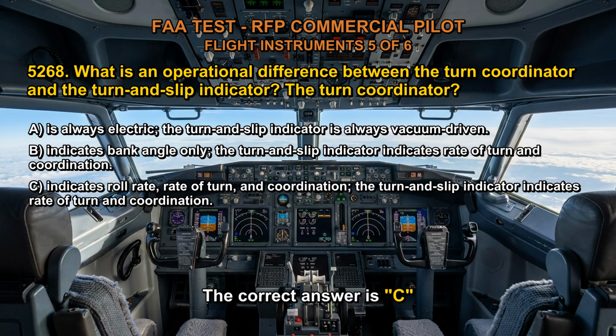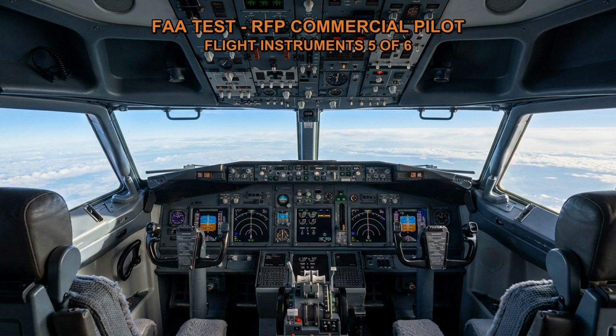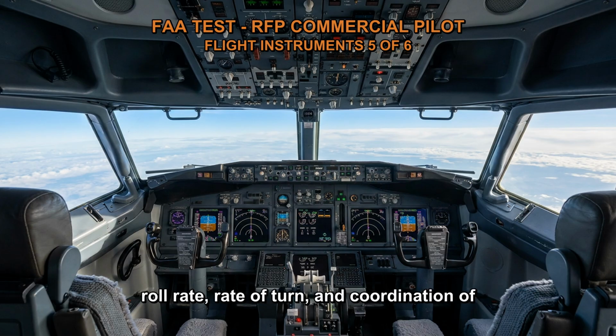The correct answer is C. The turn coordinator and the turn and slip indicator are both flight instruments used to indicate the aircraft's turning performance. However, there are operational differences between the two instruments. The turn coordinator provides information about the roll rate, rate of turn, and coordination of the aircraft. It typically consists of a gyroscope that senses the roll and yaw movements of the aircraft. The turn coordinator displays the rate of turn with a needle or a symbolic aircraft representation. It also indicates coordination by using a ball or similar indicator to show if the aircraft is coordinated or slipping/skidding.